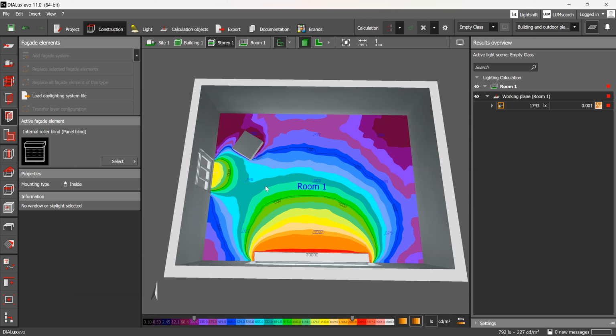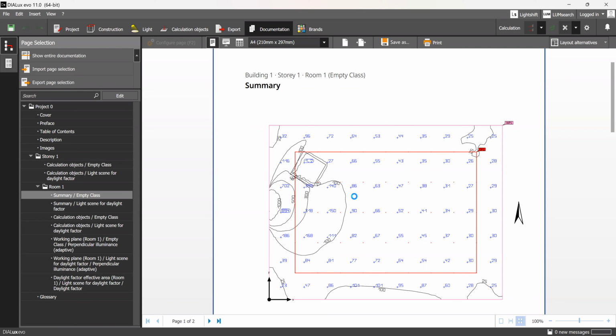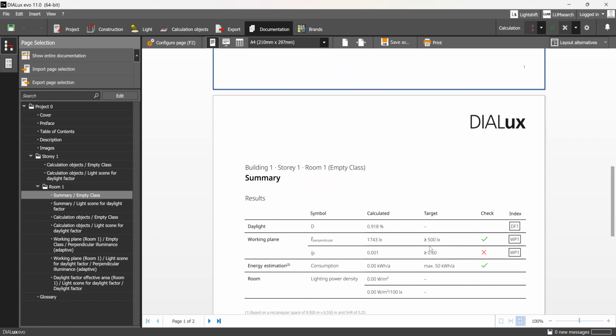Did you learn where to find the illuminance level when you're carrying out a simulation? It's in documentation, illuminance level. The available information on it provides you a summary. It's updating. You see, it shows the contour lines, it shows the table and everything. Where you can find it is this 500 lux.